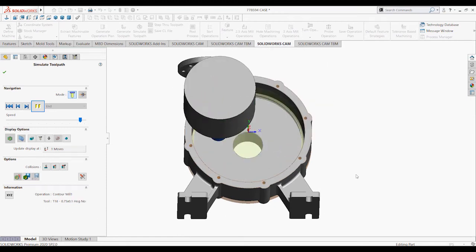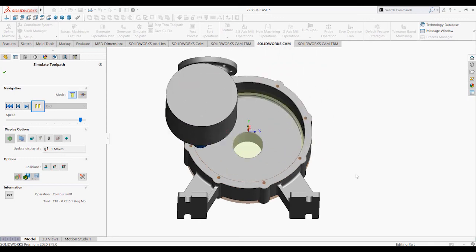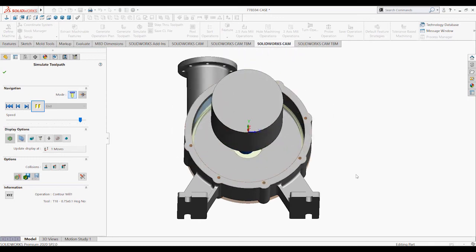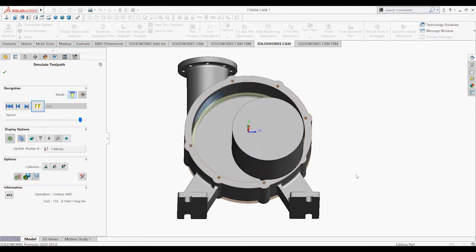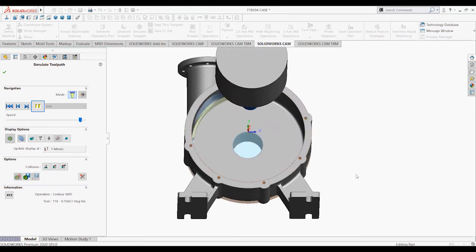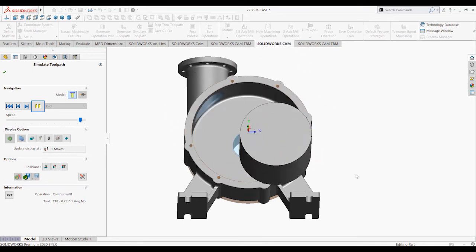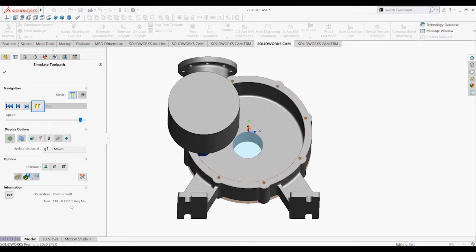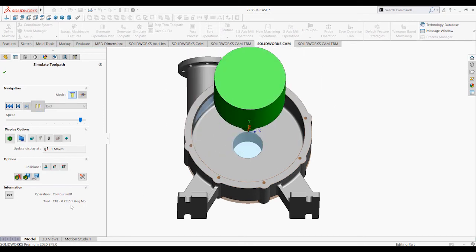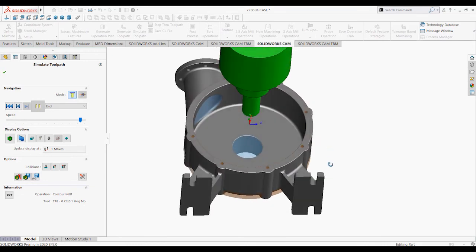Next, we're coming in with our finishing toolpath. That contour mill is using a 3/4 inch hognose. It's automatically identified the bottom radius of the circular pocket, and it's selected the appropriate tool. So a hognose tool with a 0.1 inch corner round on it. So now we've finished milling that circular pocket.